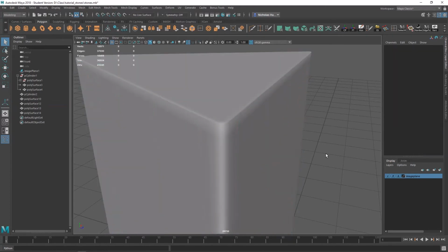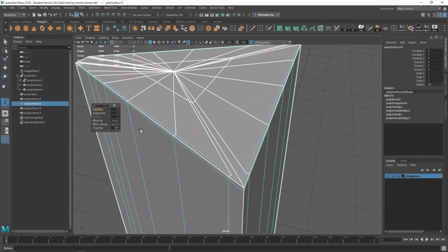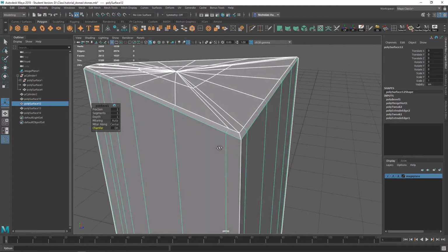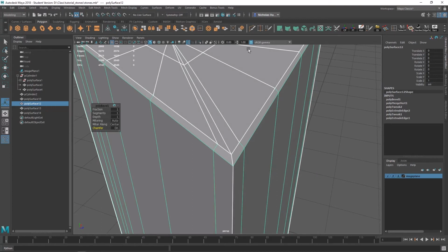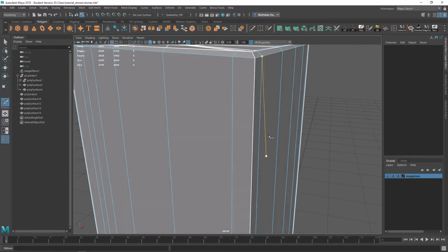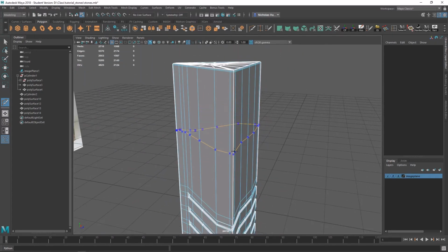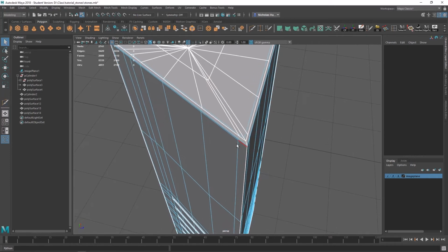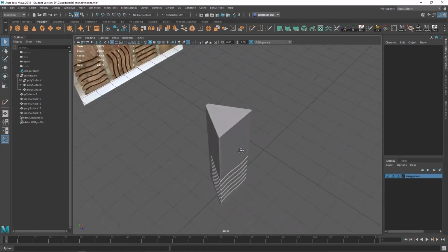So let's go to object mode, preview. It's probably too tight. So back to T, I'm going to turn chamfer on. Smooth. That might work. So one way to fix that is, I'm going to select the multi-cut tool up here. Going to hover over any of these edges right here, hold down Control, drag out an edge to about here, and one underneath to about here, just to hold this shape. And for funsies, one in the middle too, just so nothing gets stretched too far. Tap Smooth Preview, and that's looking a lot better.